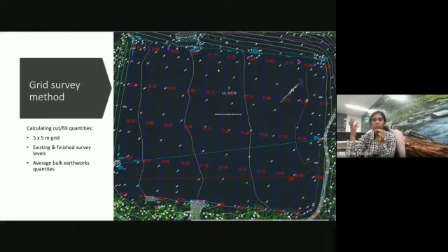This is what I mean by how many cubic meters of soil needs to be cut. I will be able to allocate machines for it, saying, okay, if it's 500 cubic meters, or if it's just 100 cubic meters, I can allow smaller excavators. It can be a 5-ton or a 20-ton excavator. If it's going to be over 1,000 cubic meters, then I have to allow for a tractor and a scoop, or I'll have to allow for an elevating scraper.